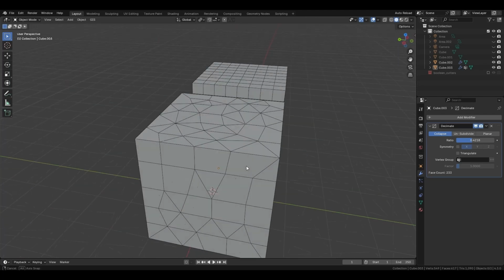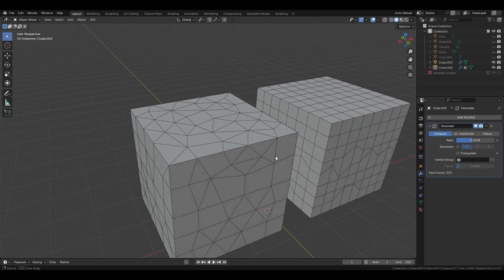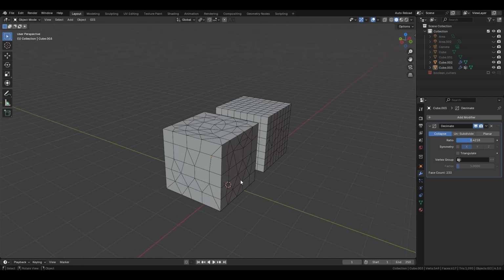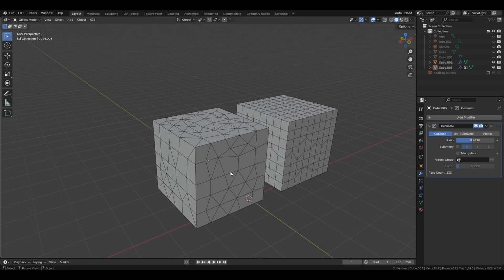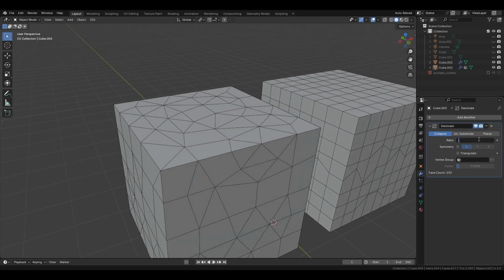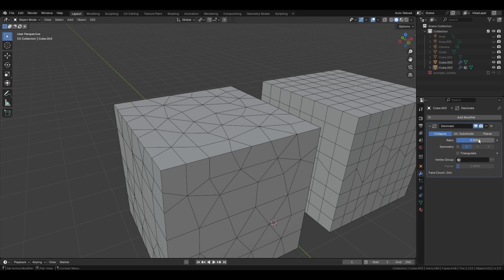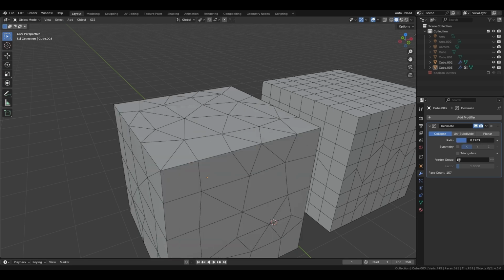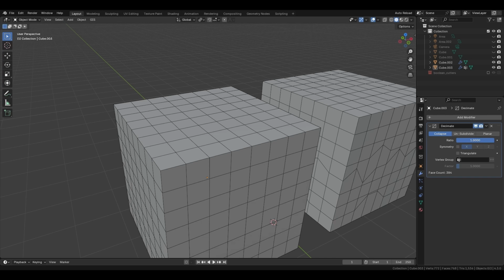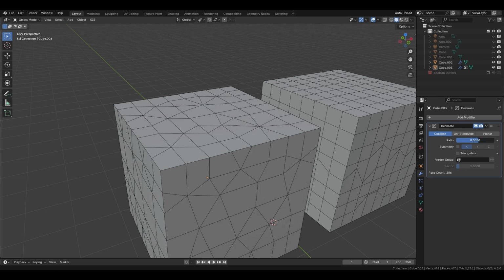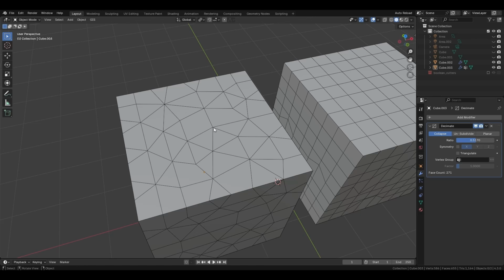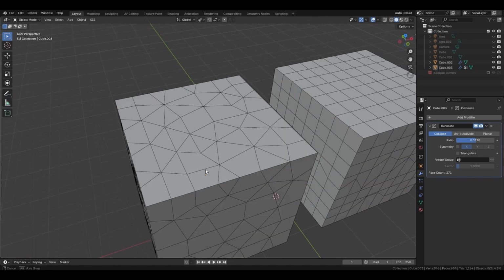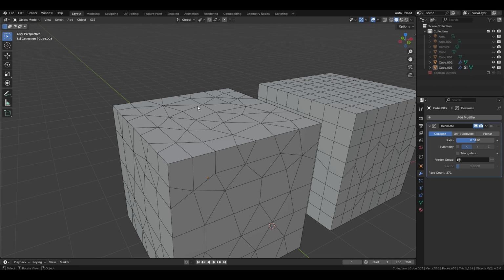This option is useful when we have a high poly object. In that time, we can reduce the geometry using this modifier. A ratio value of 0.5 will be best. In case you bring this to 0, then there will be nothing. So while changing the value, don't make it so low. If you use the collapse option, then your faces won't be quads, some will be triangulated. See here, this is triangulated, this is quads. Likewise, everything will be changed. But if you need to reduce the geometry, that time it will be useful.